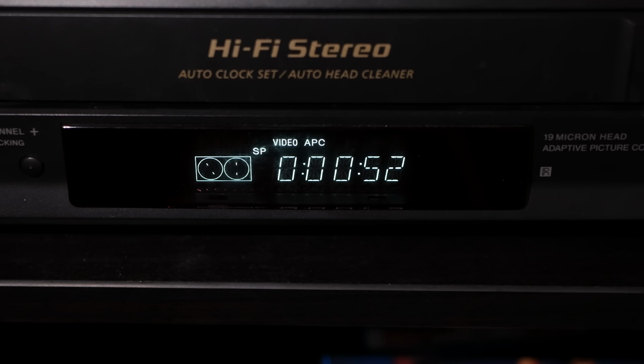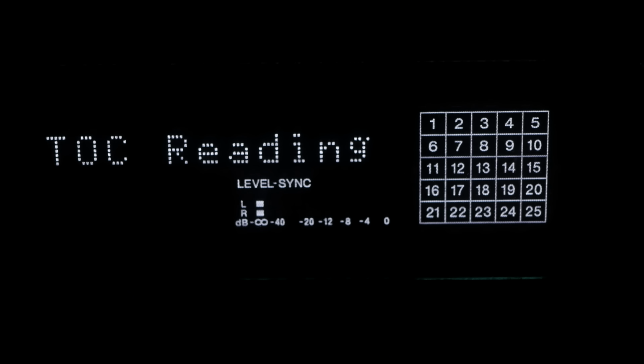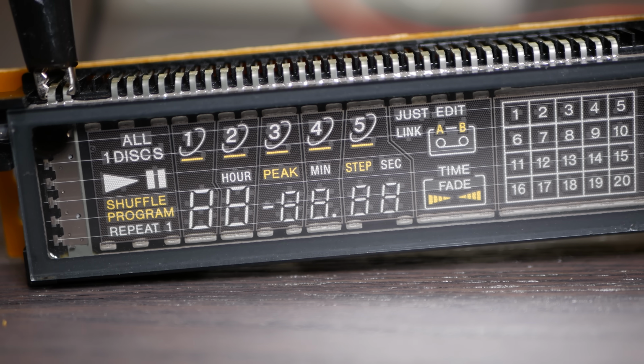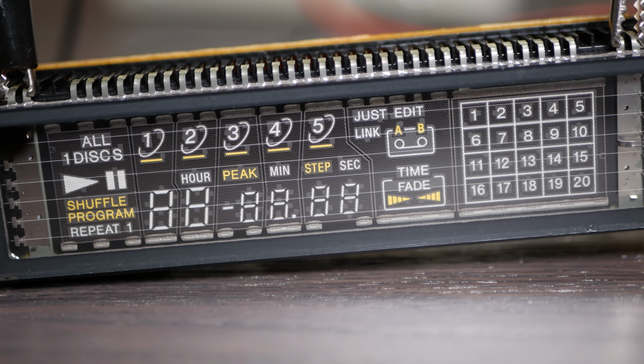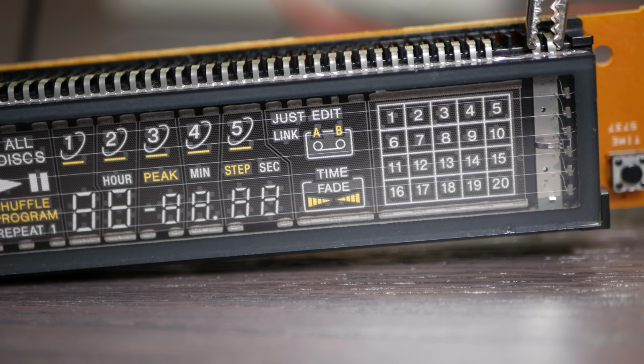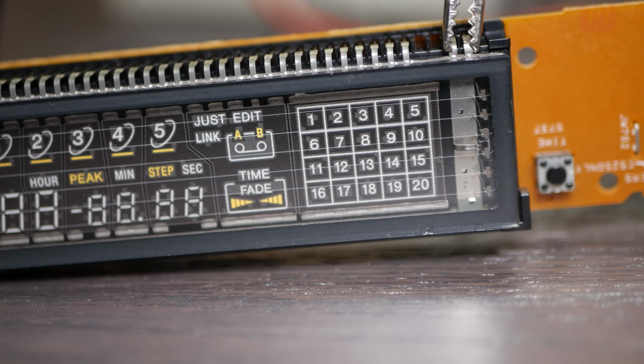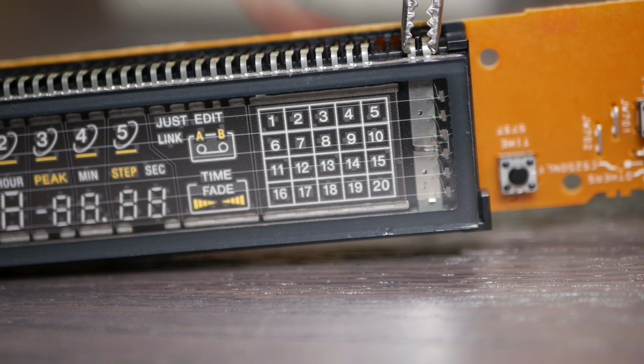You might have 8 7-segment displays all in a single package for a calculator, or even dot matrix alphanumeric displays. Through multiplexing, a technique where the entire display is broken up into several sections addressed one at a time in rapid succession, we could make very complicated and very customizable displays, featuring custom graphics and multiple colors, all with excellent readability, longevity, and simple control circuits.